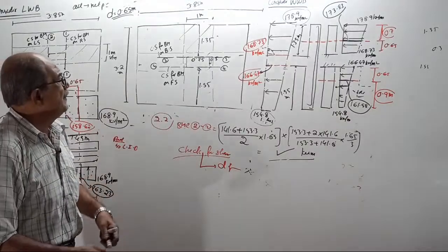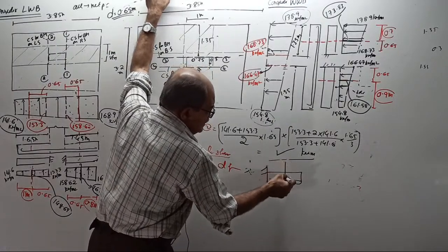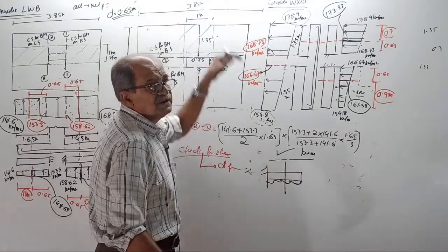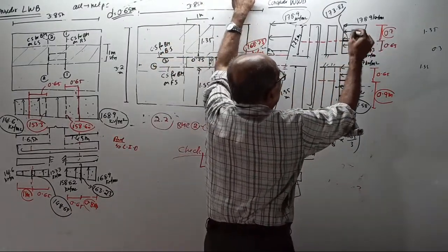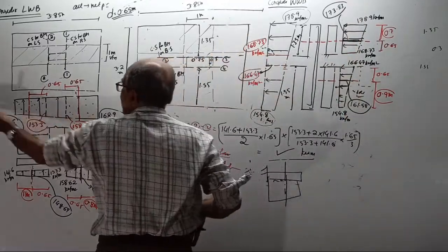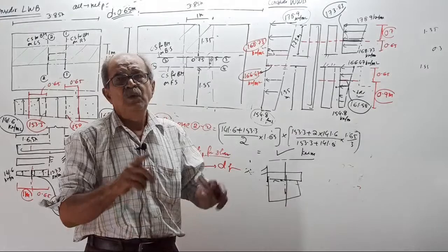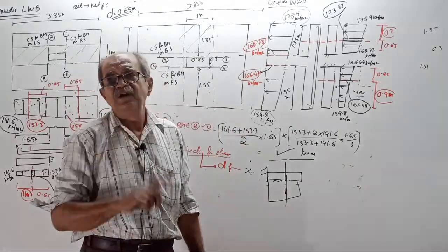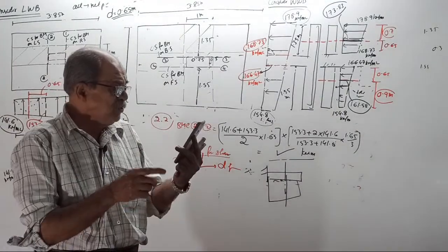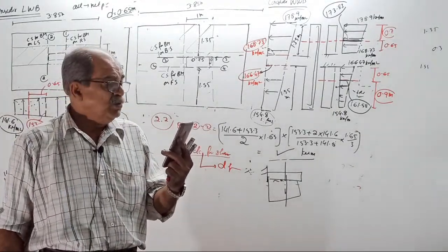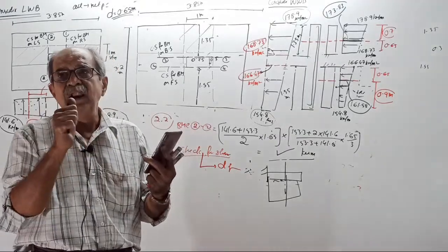Okay. Now be very careful. When you have a cantilever this way, if UDL is there and I want shear force here, only this much load, that is, the intensity in that length. But now you got trapezoidal loading. Therefore, when you want shear force here, look from the free end side. Consider only load, not moment. Only load means only what? Tell me. Only up to the free end.